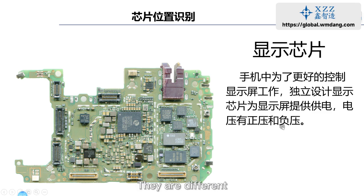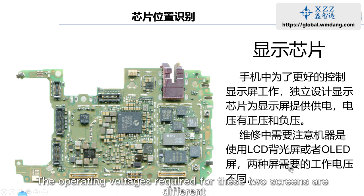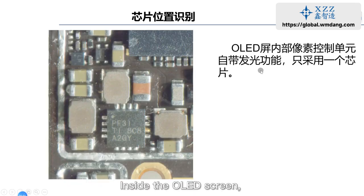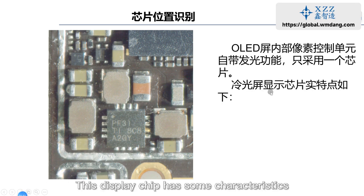They are different. During maintenance, we need to pay attention to whether the mobile phone uses an LCD screen or an OLED screen. The operating voltages required for these two screens are different. For example, the picture on the left shows a display power supply chip. Let's take a look. Inside the OLED screen, the pixel control unit has its own light emitting function, using only one chip.